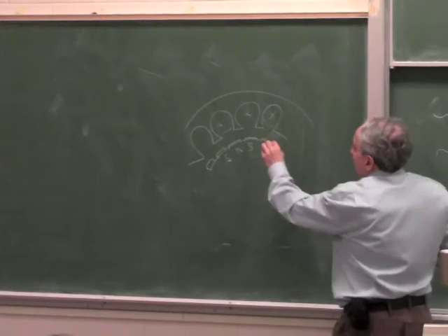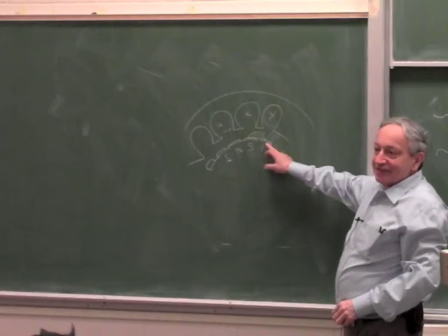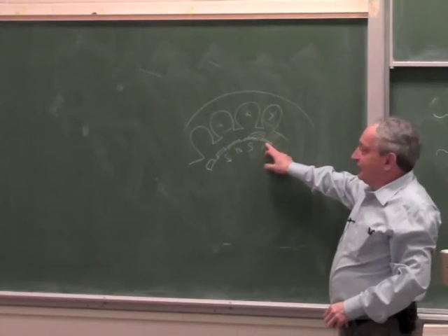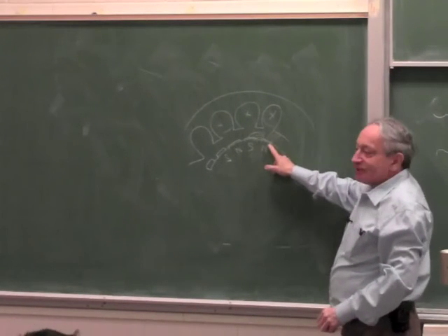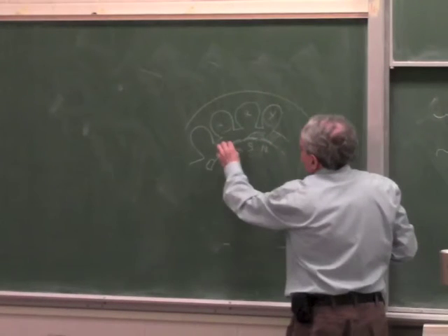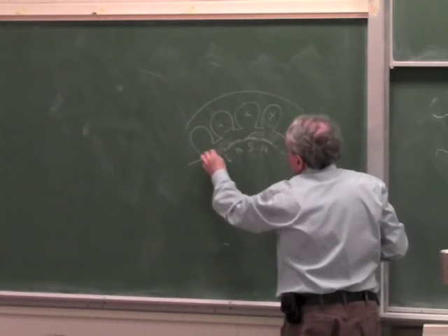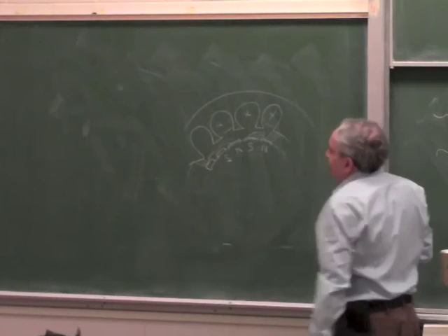But there is also flux going like this, because these poles are very close together. If the air gap was 0, this flux would be much smaller than this flux. But because of mechanical constraints, there is a lot of flux which goes like this instead of going where it should, which is to the field.